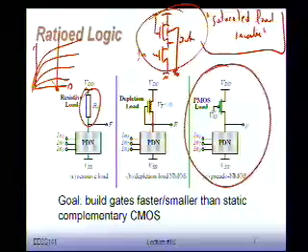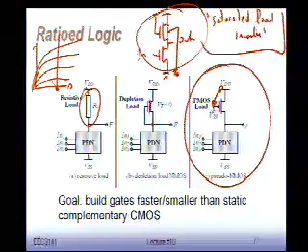There's another option, and this is probably the better option, which is to use a PMOS load. For the PMOS load, you take a PMOS transistor and you connect the gate to ground. Which means that in this case, the VGS of this device is always going to be equal to VDD. Okay?